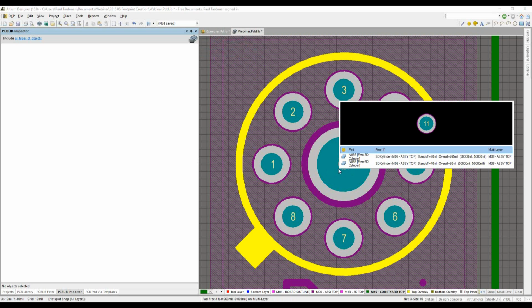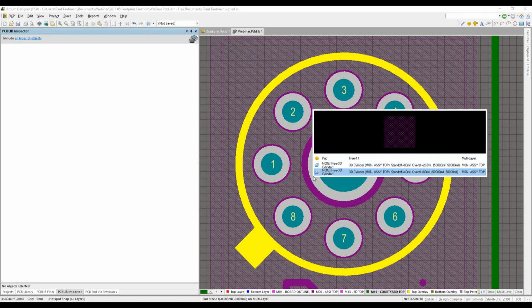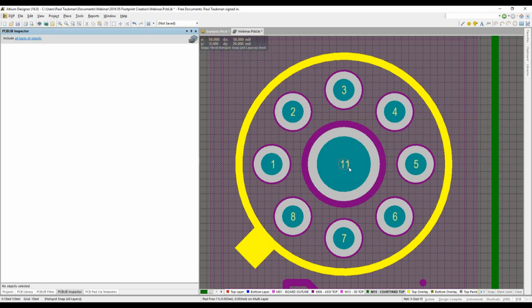Now the other thing people say is, well, what about tenting it? Well, you can tent it, which means I put the solder mask on the bottom. But how strong is that solder mask going to be? You're trying to treat this like a paper cup, and it probably won't work, because with the heat and the amount of pressure going on, if you put solder paste in there, who knows if that solder mask is going to hold up during the assembly process, because it's very, very hot, right? And if this is going through a wave solder, I don't think it's going to hold up at all.